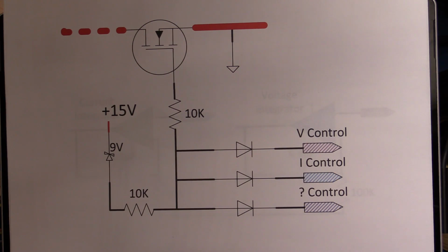So it will be an easy way of having a computer controlling the power supply, but being able to set a maximum current and a maximum voltage with a manual potentiometer on the front panel, to prevent maybe driving too much power into a sensitive circuit, giving you control.